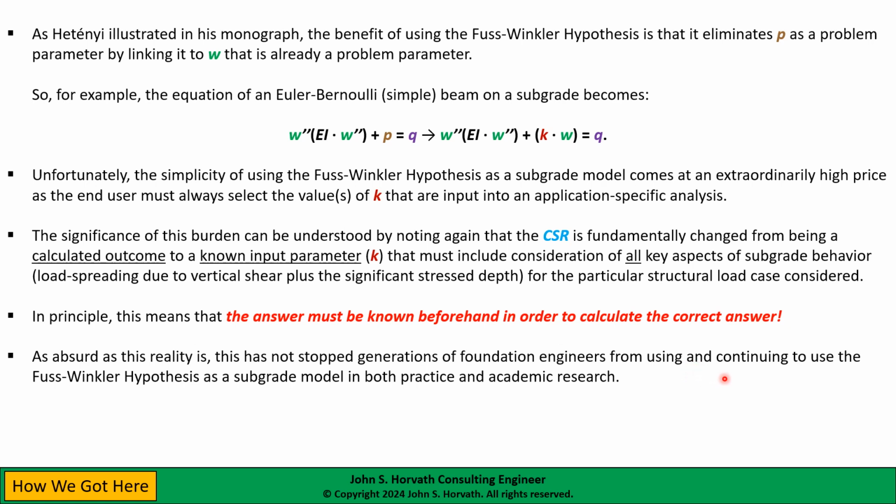research. If you don't believe me, I suggest you simply go and Google subgrade reaction, Winkler, soil spring, any of those terms, and you will see constant publication to the present of people using this simplistic spring model. And I don't think they appreciate that basically it means that if they're going to do this, they better know the answer beforehand if they want to calculate the correct answer.